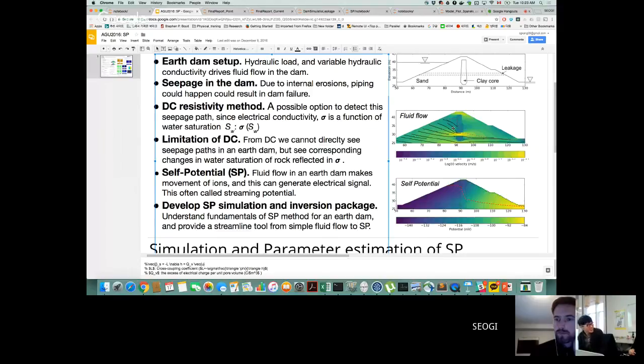How did you set up that model? I set up a boundary condition here, I put a Dirichlet, and then I put a Neumann until here, for all those boundaries. There are a little bit of details because I had to define the boundary condition inside of your mesh. So I'm actually not solving this part, but only solving inside of your mesh. So this is a tensor mesh? Yeah, so basically zeroing out things. Exactly. It's a little bit annoying. But it's not necessarily wrong. It's not telling you the amount of water, it's just telling you if there was water, it would flow faster.